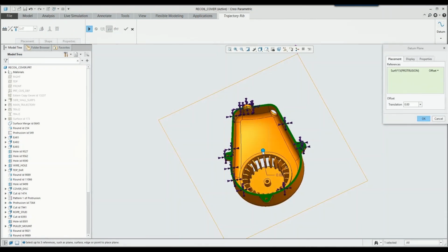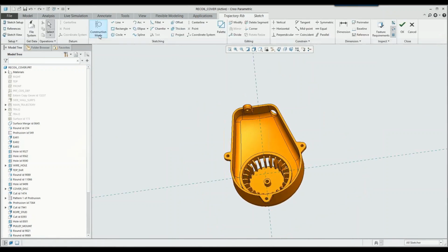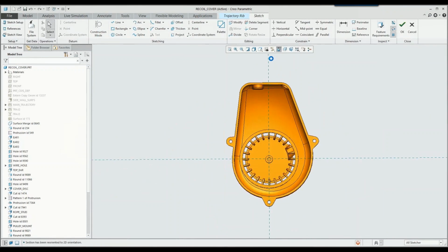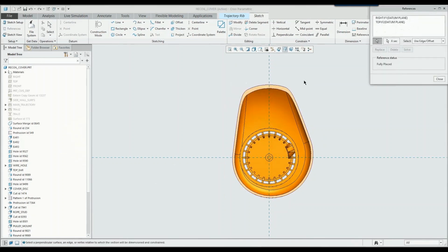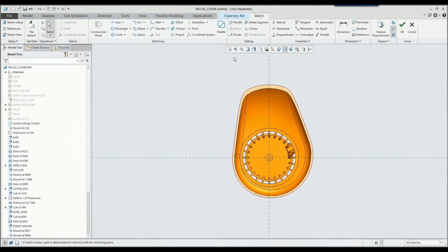If you work with sheet metal components, and you've not used this tool before, it's a great little tool for adding in multiple ribs across, let's say, plastic components or whatever it is. So we're using a defining sketch here, and some of the later Creo tools available to us. I'm just going to sketch out my location for my ribs here.